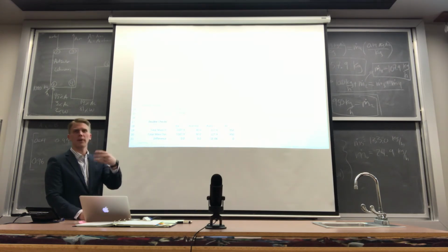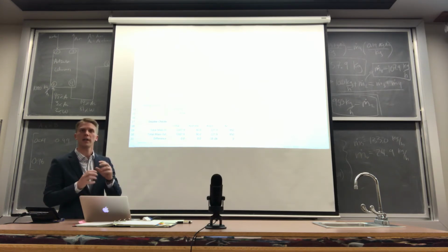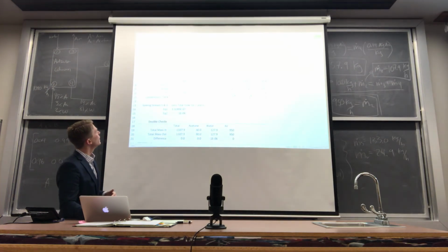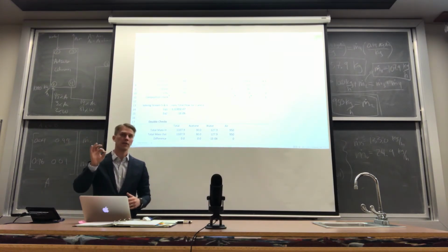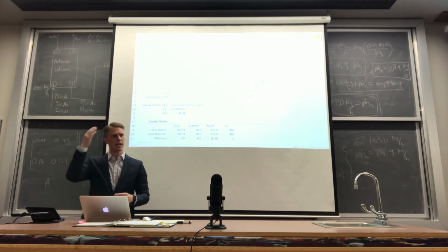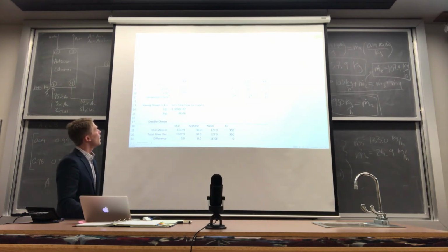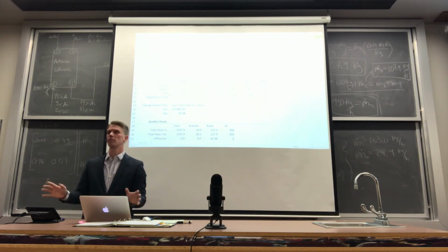And then for MATLAB, if I write in MATLAB, I be sure I comment everything and I try and break it into sub-blocks so that I can troubleshoot one sub-block that does a particular action. Now, the reason why I do it this way, I have an input cell, a calculated cell, and a constant. Every single one of those cells requires a certain troubleshooting task. So it takes away an element of my thought process for me to get to the right solution. On an input cell, all I have to do is ask, did I put in the right number? It's as simple as that. I know that every input cell, I can just change the number.